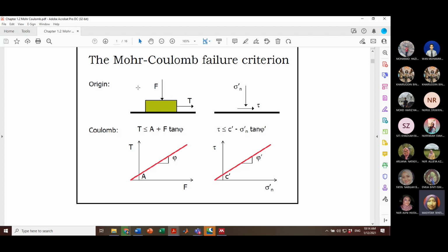This is what we have originally, and how it is turned into stress. Stress is a force acting on a perpendicular surface area, so F over A gives you the normal stress. The same goes for T, the shear force. Then you know the respective area subjected to this load T, and now you can have the shear stress.